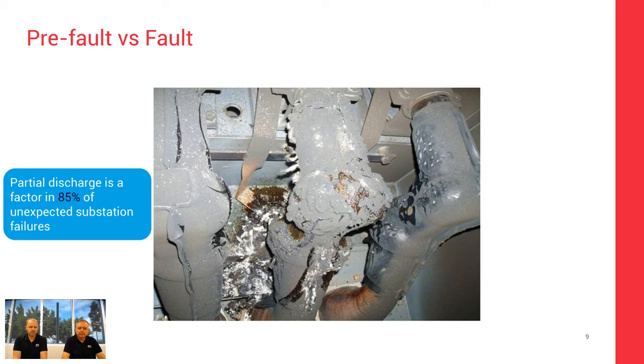You've got overtime, you've got unexpected switching to do, lost production or lost elements of the network. We've got the carbon generated from the fault area now. So that carbon, the dust, the debris has now gone up the bus bar. So it's affected larger components, maybe down into the CT chamber, down to the circuit breaker, the cable box, depending on the configuration of the switchgear.